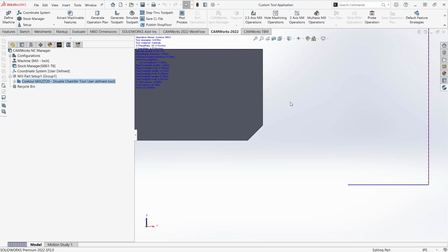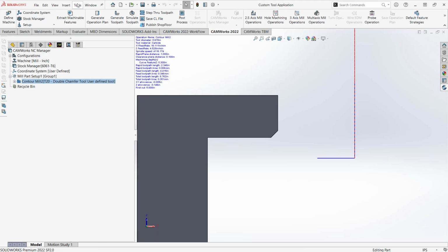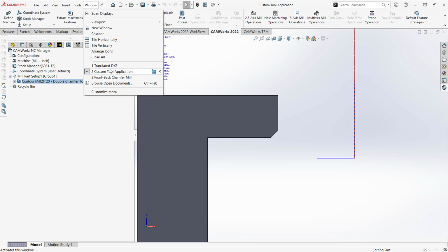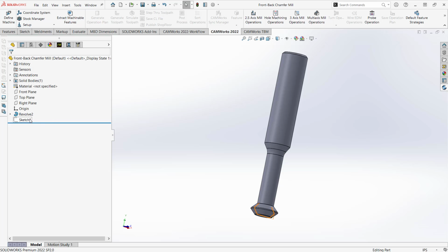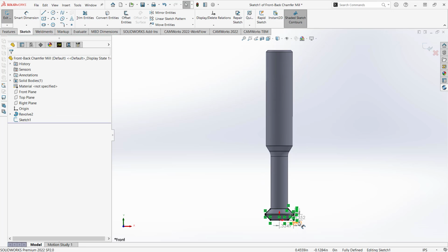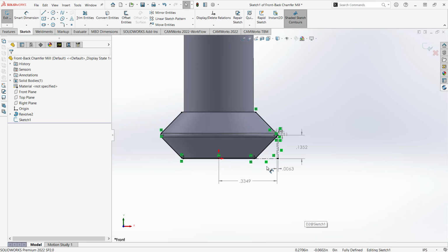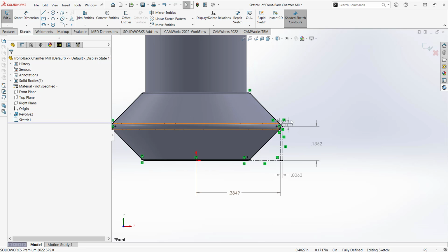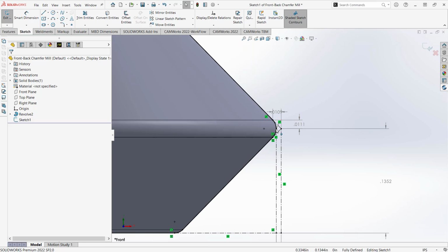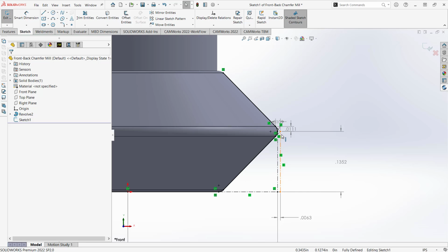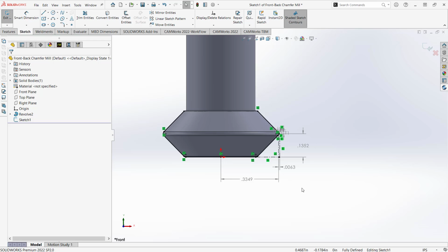Now, one quick little thing I would say to help with that idea of the shifting is there's no real guesswork there. All you have to do is go back to your tool definition, and you can create a sketch like I've done here, or I just take the dimensions right off there. So using these dimensions, I know from the tip here, for instance, this tool is unique in this manner, because the radius is making the cutting diameter smaller than this actual mathematical point here, I just take all these dimensions into account and then define them as my allowances. And then that gives me my exact movement of the tool based off the shape of the tool.